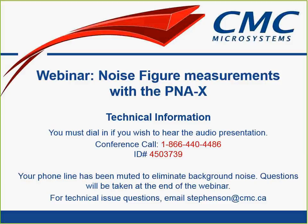These noise figure measurements can also be applied to connectorized and on-wafer devices, and we will show how the PNA-X noise figure solutions improve the measurement uncertainty. As a bonus topic, we will explain some of the extensibility of the PNA-X noise figure solutions to measuring noise parameters. In CMC's test pool equipment, we have the Agilent N5242A PNA-X analyzer to measure up to 26.5 gigahertz, and also the scalar measurements described today.